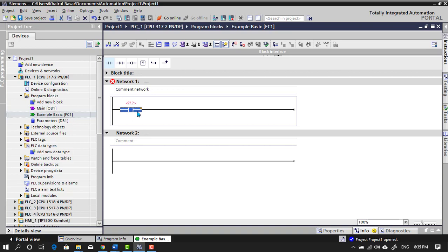Now this actually has multiple types of variation of instructions. So normally open, normally closed, NOT is the invert instruction, positive pulse, negative pulse. So you have 1, 2, 3, 4, 5 selections from one instruction. Button, yeah, I would say this is kind of a button actually. Now this one is also available inside this.